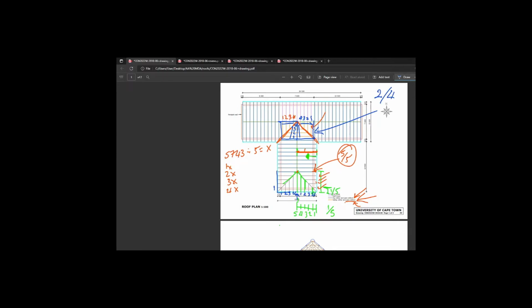Okay? Let's jump across to our hip rafters. 1, 2, 3, 4. So I'm counting again. 4 and 4. Okay. And 4 and 4. Same story. 2 and 4. Now, I've made this process longer than it needs to be. As you get better at these things, you should just see clearly that there must be 2 for every valley or hip rafter.